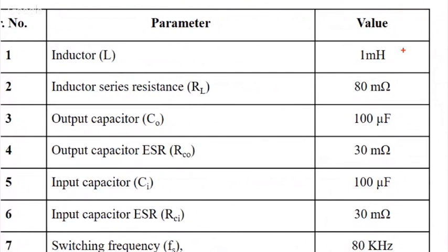Here you can see this is the inductor value and this is the capacitor value we got. The input capacitor and output capacitor have the same value, and that also we found from the calculation. But the main challenge we faced is that all these inductors and capacitors, when real, have some ESR, an effective series resistance. You have to find this resistance, otherwise how your hardware will perform, you will not be able to see in simulation.